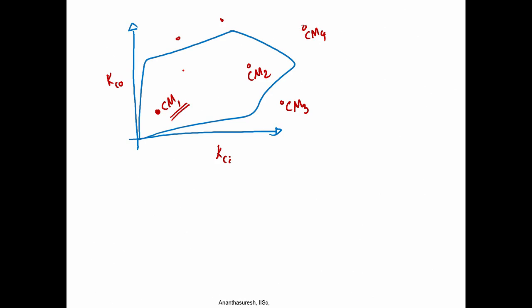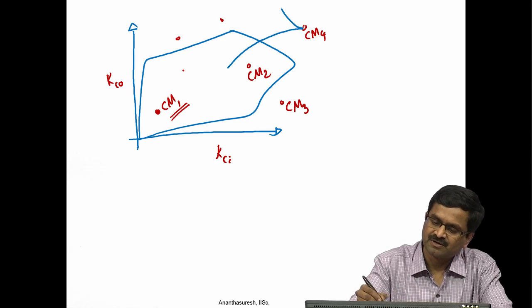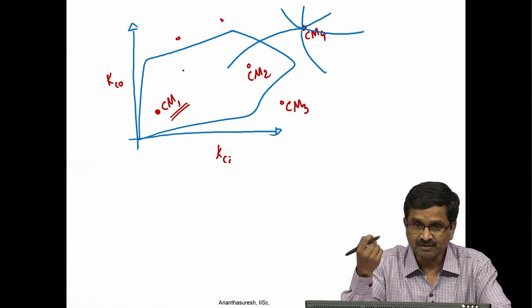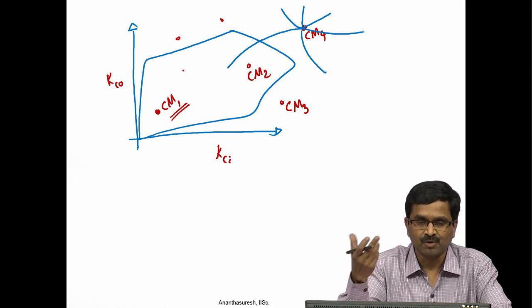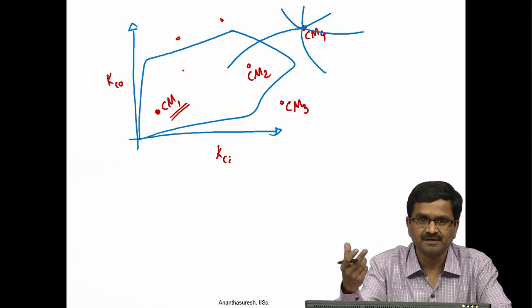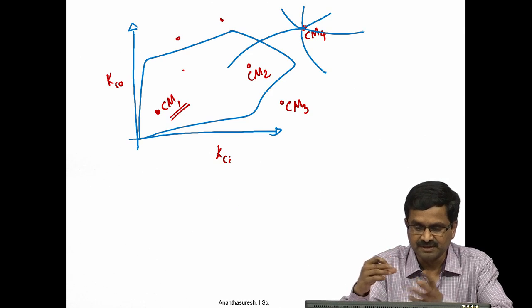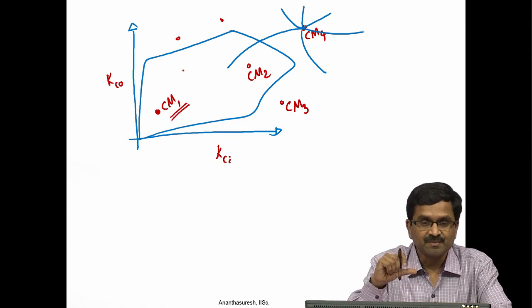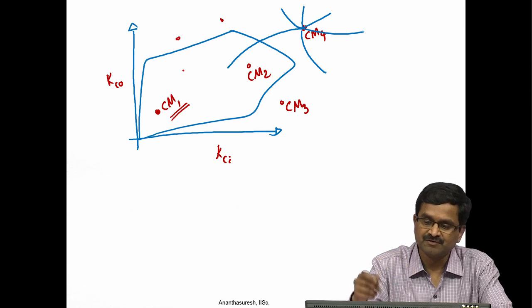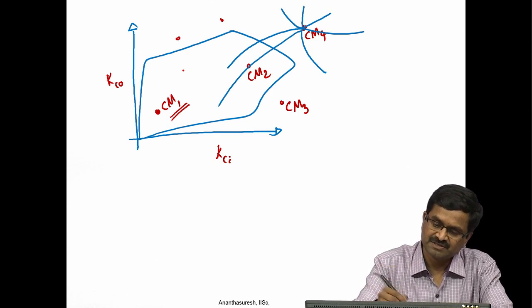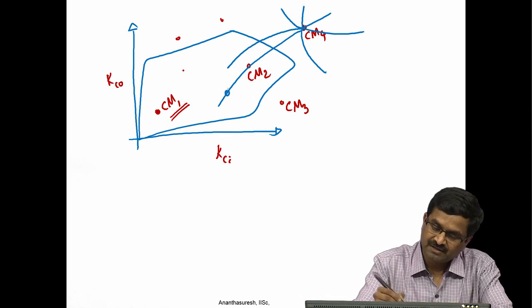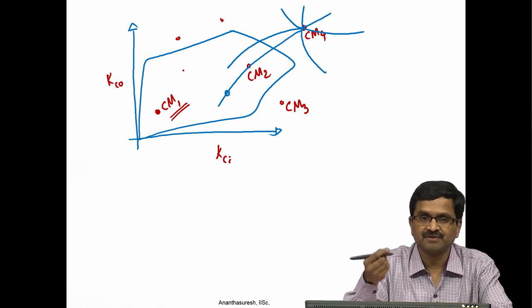If none of the things that are inside actually match the n value also, we go to something that is not inside and try to bring it inside by drawing some parameter curves. So, we vary various parameters like the width of the beams, overall size in x and y, change material, change the x and y sizes simultaneously, or cross section and this simultaneously. We can generate all of that and get it inside. Once it comes inside, we may find that it satisfies, and again we have to satisfy the n value. So, we can also do the redesign.